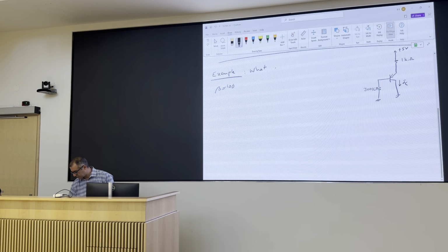So I can easily measure the collector voltage, I can easily measure the emitter voltage. If I do that, and I measure something on the order of 0.1, 0.2 volts, I may be in trouble. Unless saturation is what you want. Right? And that's saturation. So when your device saturates, you have a few things to check for. One, VCE is small. You're getting close to 0.1, 0.2 volts. And it's not VC or VE, it is the difference between them, right?